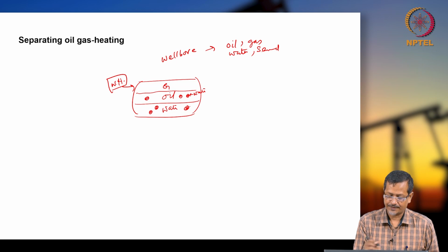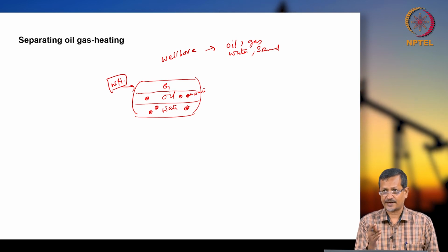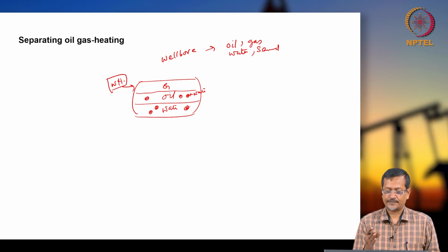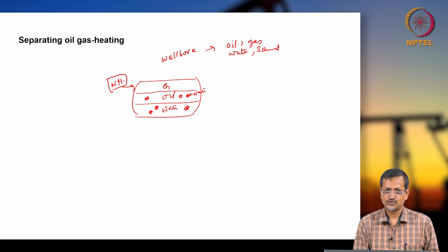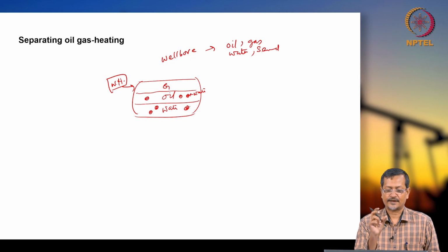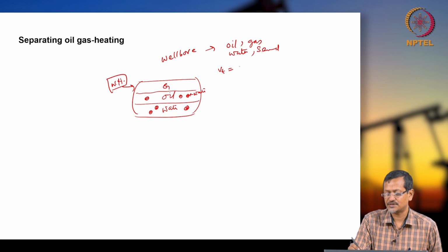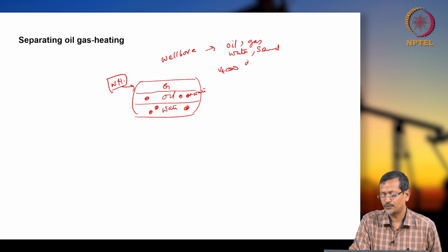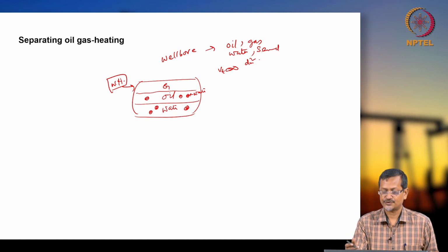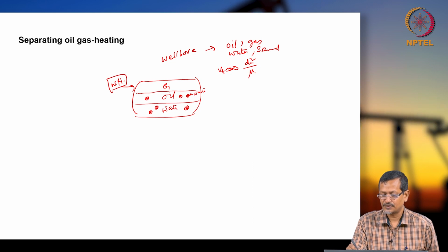water. If you want to separate, there are several mechanisms we have discussed already. Electrostatic coalescers are there, mechanical coalescing systems are there. You have chemical mechanisms to change the fluid surfactant property, and you can get bigger particle size, because you have seen this Vt, terminal velocity, is proportional to dm square, the droplet diameter square, and inversely proportional to viscosity.